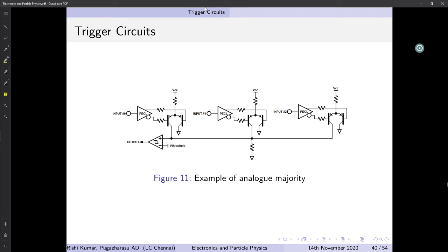However, it does result in a few issues. So we must use something that's called transmission line theory, which is a mathematical model that the designer must use to implement proper impedance matching in order to avoid reflections of this signal, because it can flow that fast.